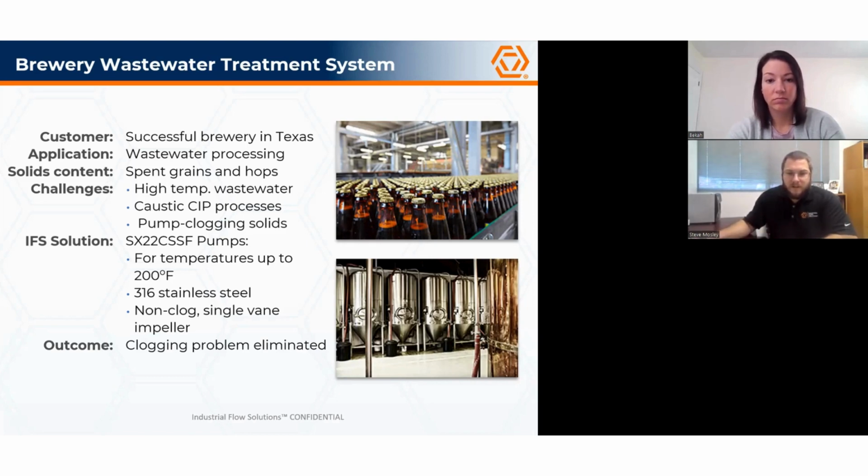Last but not least, the SX22 CSSF includes a proprietary high temperature motor design, which allows the pump to operate continuously in liquids up to 200 degrees Fahrenheit, thus allowing the pump to handle the hot wort and hot CIP cycles which enter the sump. Since the installation, these pumps have provided more than 4 years of trouble-free service.